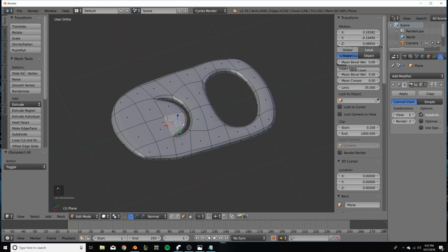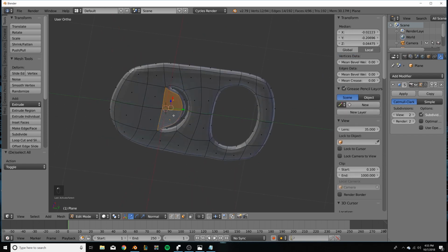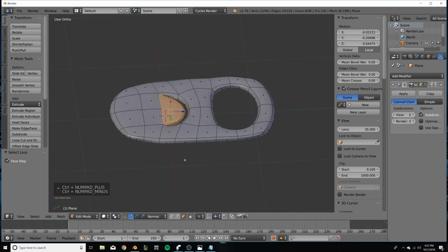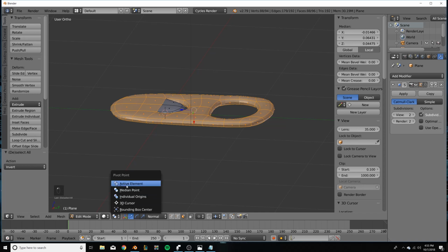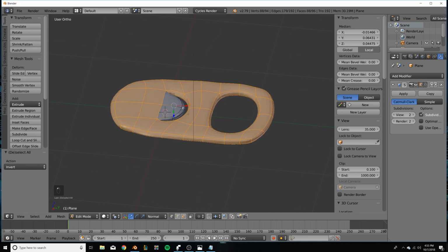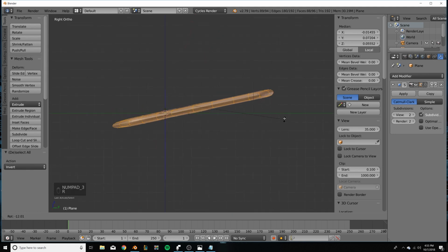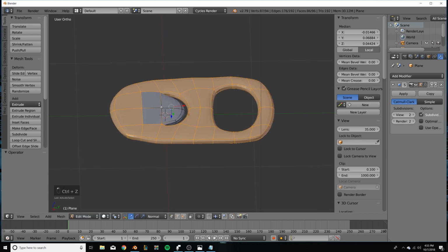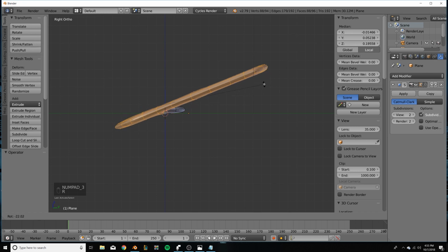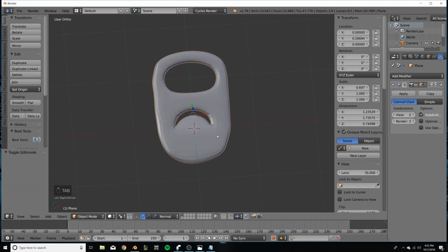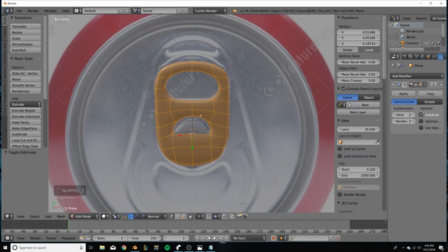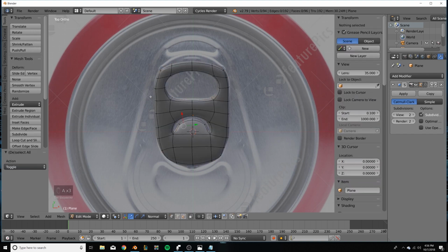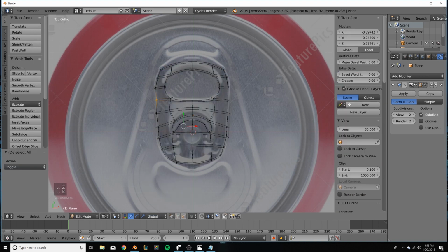So let's go ahead and select these, hit Control plus, and then Control minus. So it has all that selected. Hit W, select inverse. Then go to active element, and click this vertice. So now this vertice is the pivot point. So hit 3 and rotate, actually, this pivot point right there. Hit 3 and rotate it. There you go. So now we have this. Go ahead and hit smooth. You can kind of straighten these up a little bit just to fix them. So they are a little crooked. Go back to global.